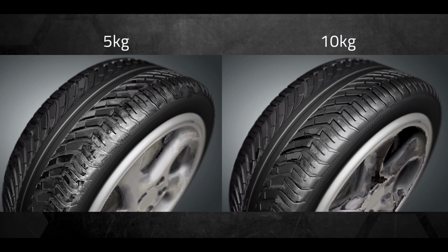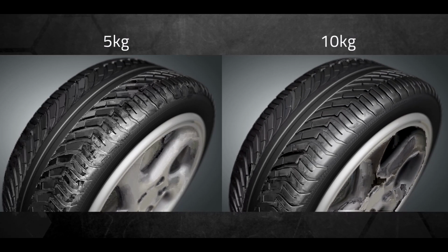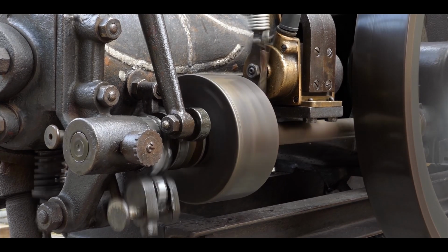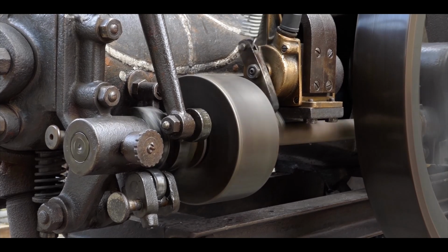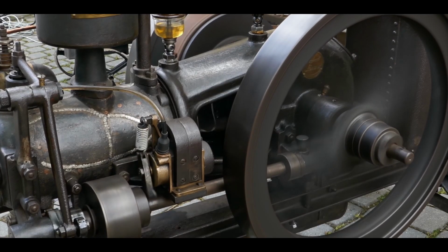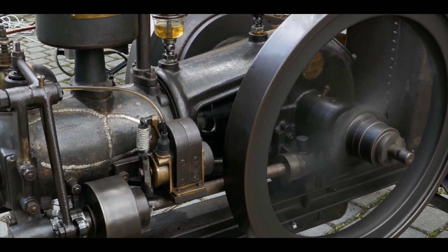And that's an example of rotational mass at work. Optimizing the shape and increasing the rotational speed will boost the energy that's stored in a flywheel. However, speeding up the flywheel increases the centrifugal forces it's subjected to, and the resistance of the material that it's made from limits the amount of energy a flywheel can store. The bottom line is, spinning a flywheel too fast can completely break it apart.